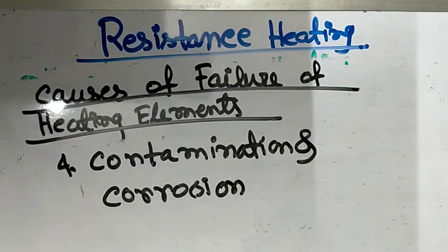Elements may be subjected to dry corrosion produced by their contamination with gases of the controlled atmosphere prevailing in annealing furnaces, or fumes from flux used in brazing furnaces, or oil fumes produced by heat treatment of components contaminated with lubricant. Of all the conditions mentioned in this video which determine the life of the element, the most critical are the temperature of the hottest point and the ratio of intermittent to continuous working.